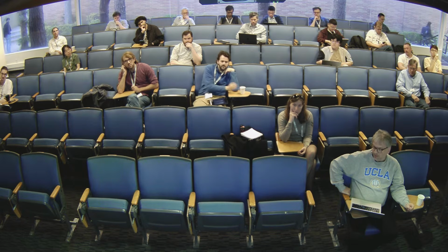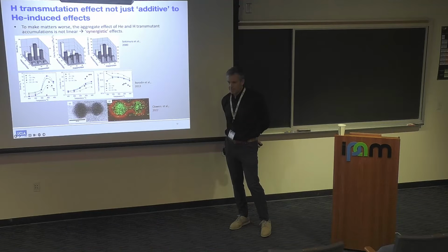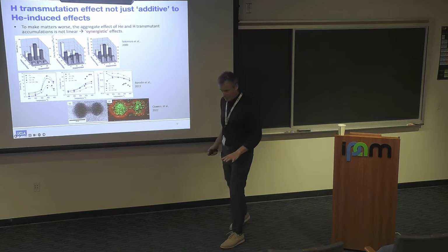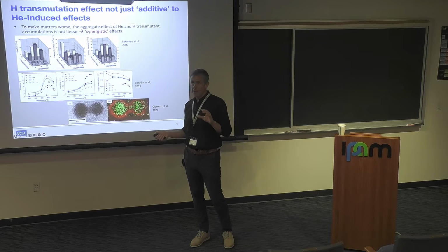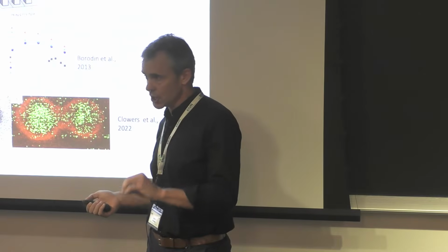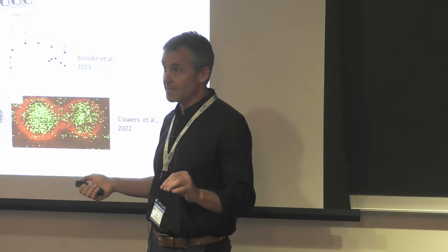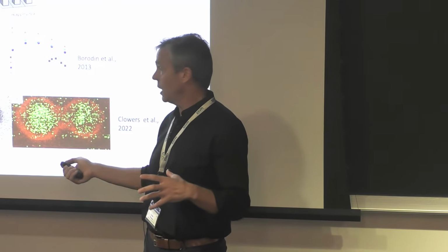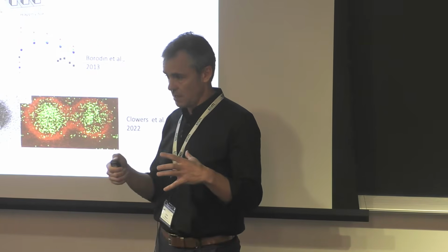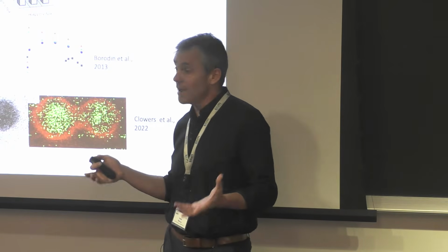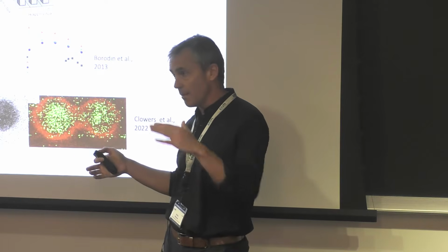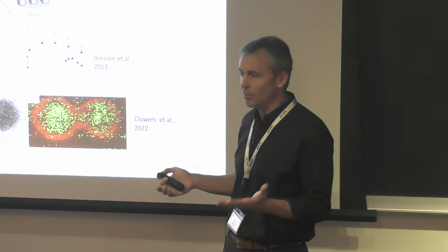And the helium bubble creation cannot be avoided, right? So swelling cannot be avoided. Is that a fair statement? Swelling cannot be avoided, but we can control right now how much swelling is produced for a given amount of helium, because we can tailor the microstructure in such a way that we prevent helium from aggregating in localized locations of the material. We call it helium management. So we can try to manage helium in such a way that minimizes swelling, but it cannot be avoided altogether.